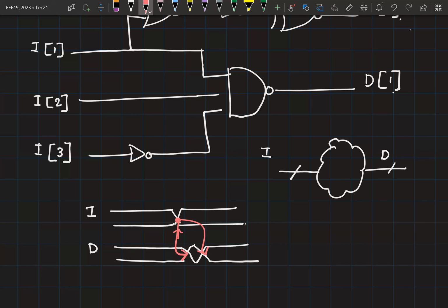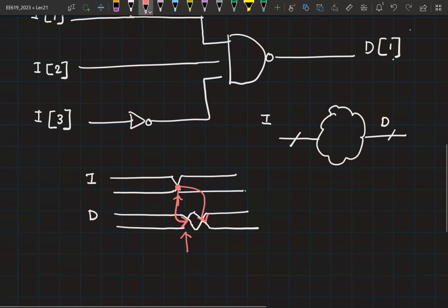What should we call this delay from the input to the first point at which the output starts to change? So there are 2 delays now. The first time instant at which the output is beginning to change, and the time instant at which the output has finally reached the settled, stable value. The 2 delays that we know of are contamination and propagation delay. So we apply the same terminology here. So this is called the contamination delay, and this is the propagation delay, TPD.